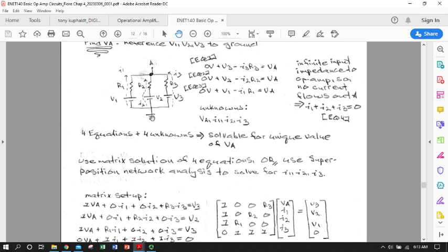and express the voltage at point A in terms of ground and voltage sources and voltage drops over the resistors. Then I'm going to sum all the currents at A using Kirchhoff's current law. Let's start with branch 3. I go from ground and I go up in voltage over my voltage source 3, and that's my input signal 3. I'm going to subtract I3, whatever current is flowing over resistor 3, and that's going to give me V sub A. And so that's equation 1 here.